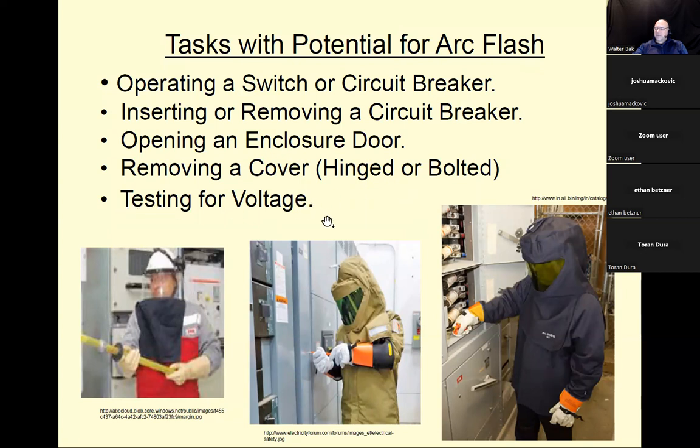And testing for voltage. Remember when we talked about the multimeters, and there being certain categories for multimeters? These are not just for fun. You're not supposed to use the tiny multimeter that you buy in a local hardware store on serious equipment, because it might not handle the energy being provided to it, and it can just blow up in your hands. It can cause more problems, because once the explosion starts, it can trigger other things. So testing for voltage can cause an arc flash.